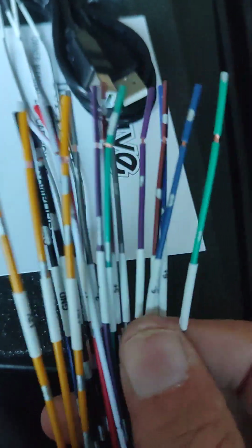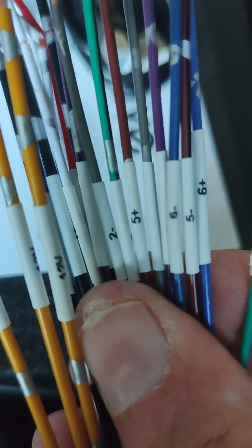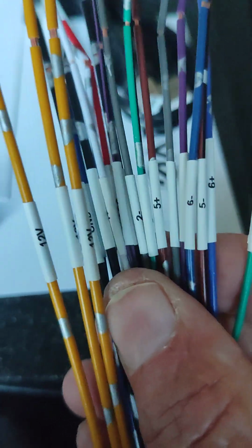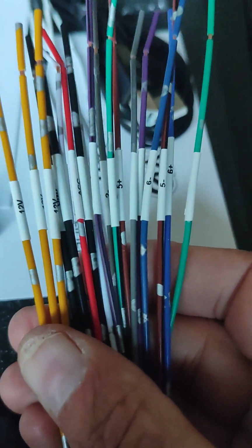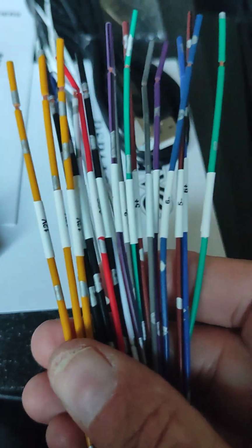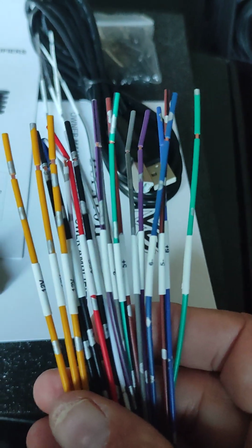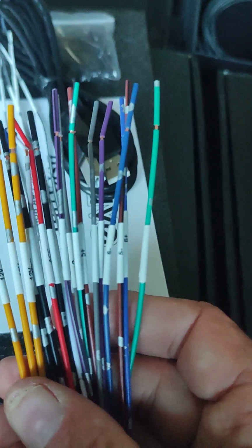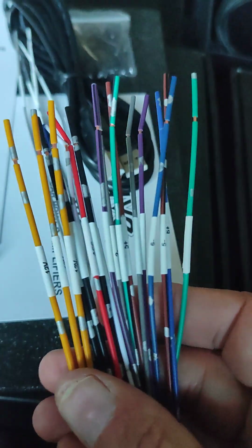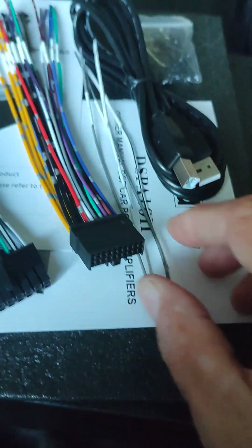These other cables are for you to choose your input stages if you choose high level from your radio. To have a guideline here, let's presume that we're going to install inputs and outputs the same way. We start with the left hand tweeter 1, right hand tweeter 2, 3 is the mid range on the left, 4 the mid range on the right, 5 mid bass on the left, 6 mid bass on the right. If you have some problem solving, another installer who takes over from you will be able to follow the same plan to check your diagram.